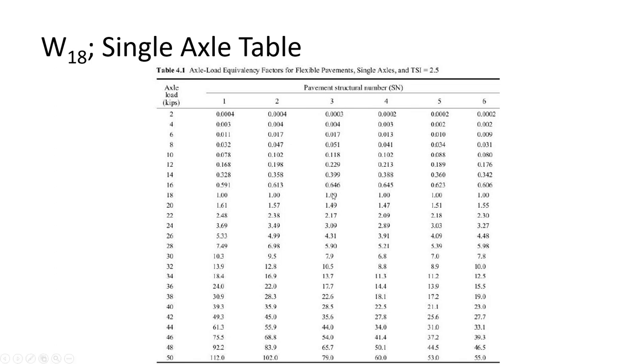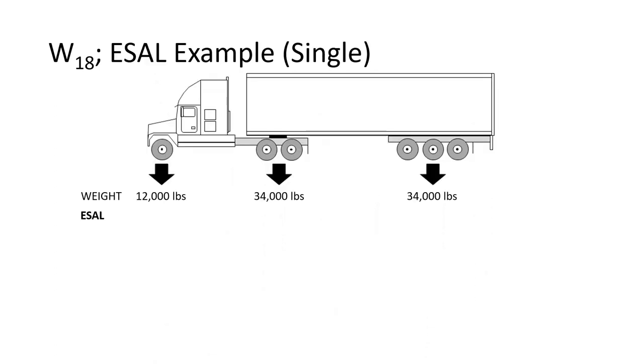So the damage caused by weight is definitely not linear. If I remember right, it's to about the 4th power. And so if you double the weight of a vehicle, it will do 2 to the 4th power as much damage as it would have otherwise. So that's why cars don't count. Essentially, only trucks do.